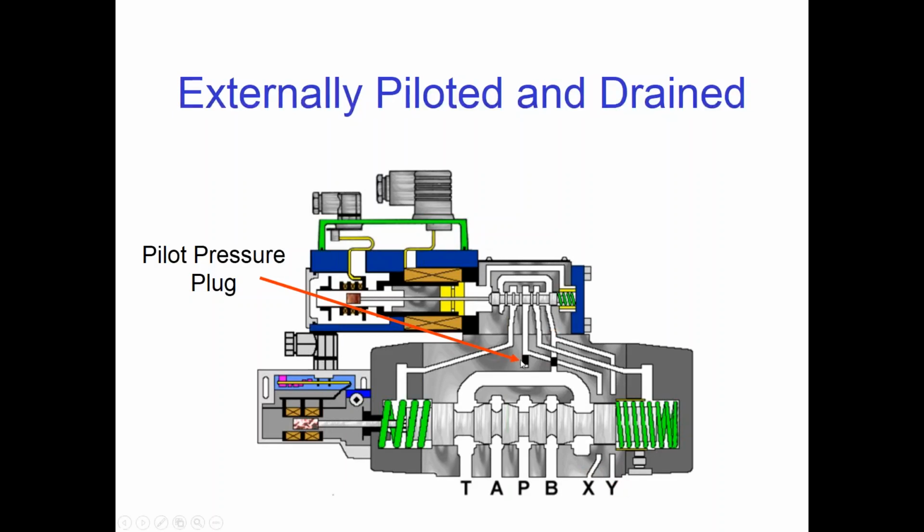Okay. So before you go sending it back and wasting a lot of downtime, remove the pilot valve and look down in these ports and see if you see the pilot plugs. Right? These little plugs, typically they're going to have a little Allen wrench hole in there, and you can screw those out if they're supposed to be out, or you can screw them in if they're supposed to be in there. This could save you a significant amount of downtime.